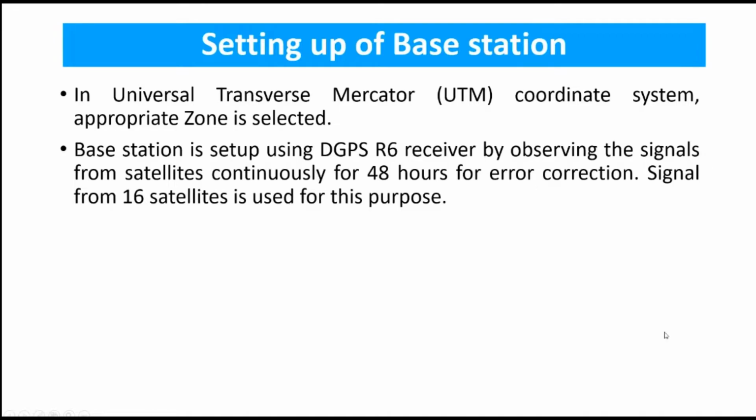and it observes the signal from the satellites for 48 hours continuously for error correction. So 48 hours are required because there is some variation in the satellite constellation.